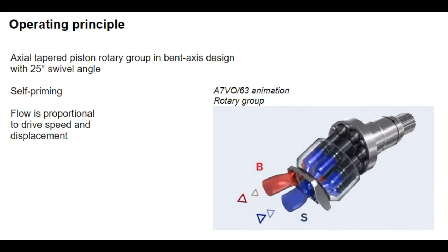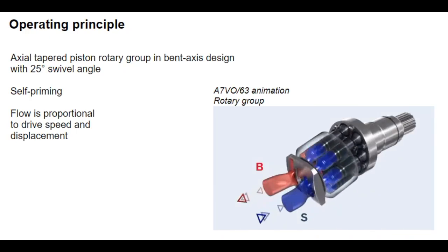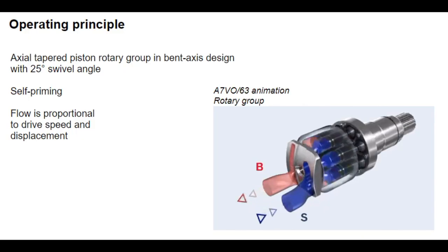Increasing the swivel angle increases displacement, while decreasing the swivel angle decreases displacement accordingly. The bearing should be flushed when operating at 0 stroke for long periods, more than 1 minute. When unpressurized, a return spring swivels the pump back to its initial position of VG max.